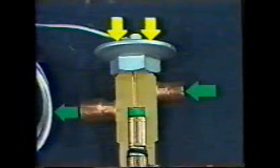As more refrigerant is vaporized, the degree of superheat at the outlet will decrease. But if the outgoing vapor isn't superheated enough to the specified degree, the spring pressure and evaporator pressure under the diaphragm will be stronger. The valve will then close to restrict the amount of refrigerant entering the evaporator coil. This will decrease the temperature and pressure in the evaporator and will result in a greater degree of superheat at the outlet.